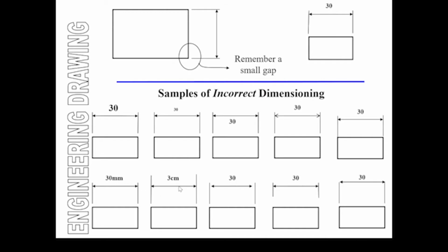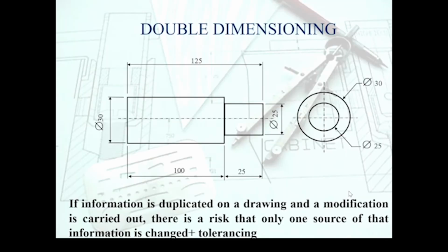UOS. Once again, we have a non-standard unit system here, and the projectors go unnecessarily past the dimensioning arrow. Here the dimension arrow is not touching the line, so once again it's necessary to be explicitly clear in terms of which space we're marking up as 30. Here the gap is too large, non-standard, and here there is no overhang. We've got to have a bit of an overhang, and the arrow needs to be contained within the projector lines.